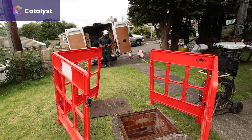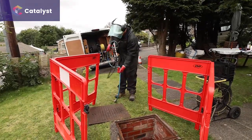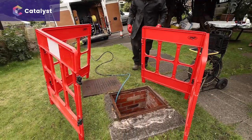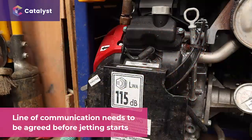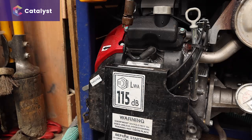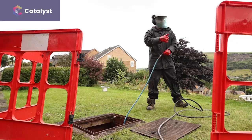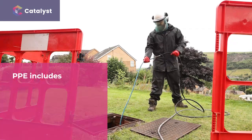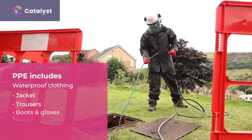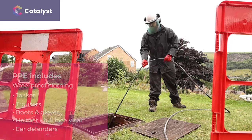When the drain needs cleaning, the engineer carries out a risk assessment and sets the site up accordingly. The engineer must choose the correct type of nozzle so jetting is carried out safely and effectively. A line of communication needs to be agreed before jetting starts with the engineers. This is usually a set of standard hand signals. With the jetting pump running and PPE on, they are not likely to hear each other. PPE includes waterproof clothing, including a jacket, trousers, boots and gloves. A helmet with a full face visor, as well as ear defenders, are essential.